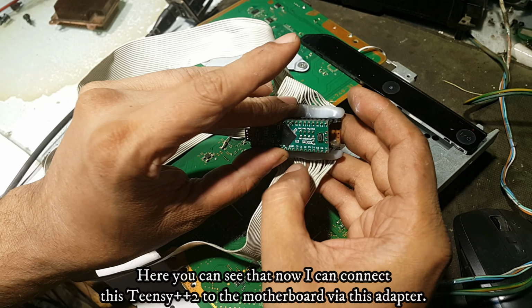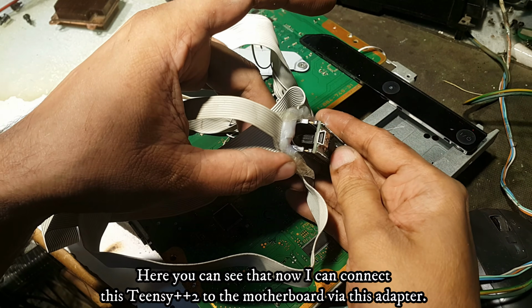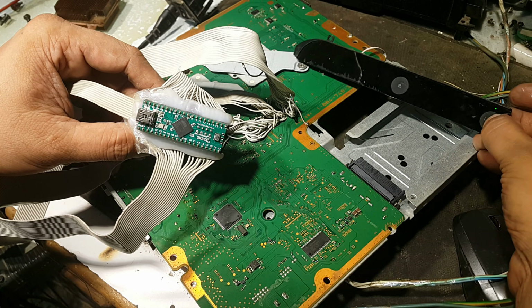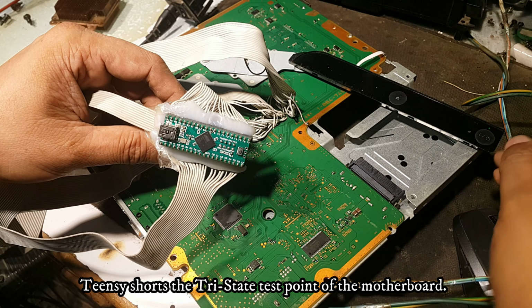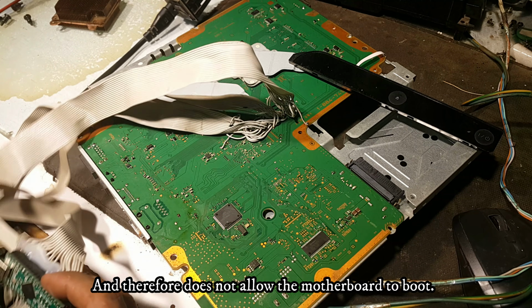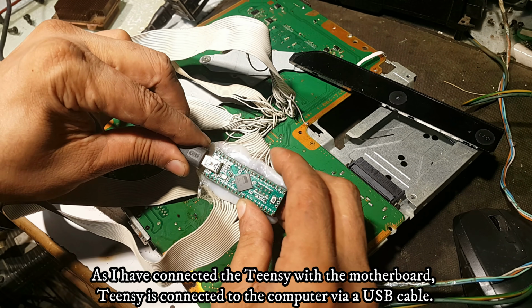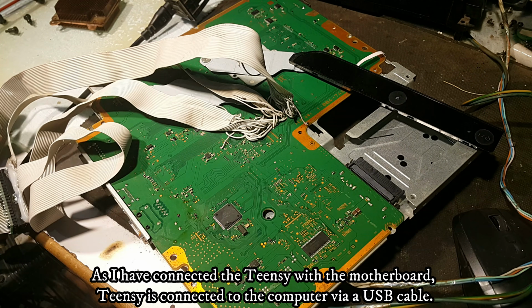Here you can see that now I can connect this Teensy++ 2 to the motherboard via this adapter this way. Teensy shorts the tri-state test point of the motherboard and therefore does not allow the motherboard to boot. As I have connected the Teensy with the motherboard, Teensy is connected to the computer via a USB cable.